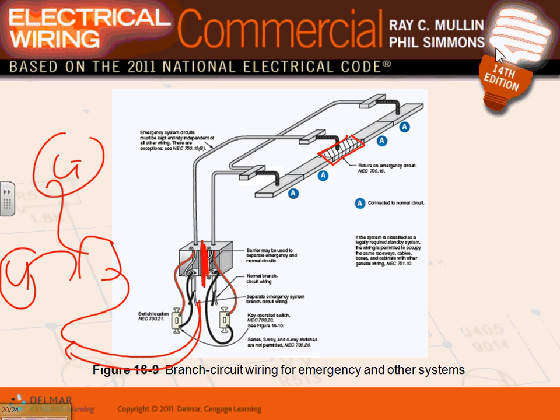What's the difference? Can I put these two circuits in the same conduit? No. Very clear. In the same box? No, unless you have a divider. They have a box that can slide a divider between them. You're good to go. Yes, sir. There are two methods of doing it: one dedicated switch, or two dedicated switches. This one is two dedicated. This is, by the way, a keyed switch. You key it on and you leave it on in this situation.